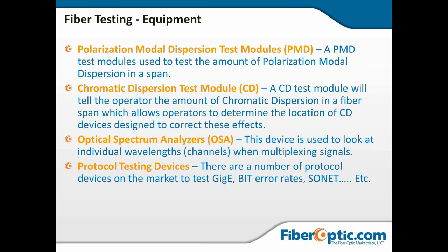And that has recently, well, not recently, but with the rise of and discovery of polarization mode dispersion and it coming to the forefront, we have realized that that's the limiting factor. PMD is going to cause us to either shorten our runs or limit our bandwidth over our existing distances, because it's just going to cause so much delay that the signal breaks up.